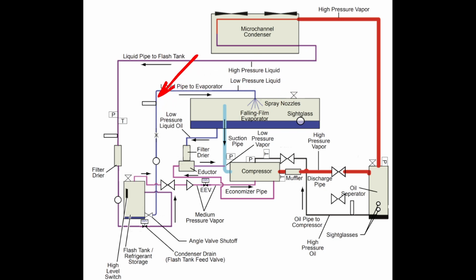Either way, our refrigerant gets injected into the top of the evaporator. There is a spray rail system in here that sprays this refrigerant over the tube assembly, and then our suction line also comes off the top of the evaporator as well. So we don't have any lines or connections here at the bottom of the evaporator except for our oil recovery tap for our eductor. So the way these are piped, I'm going to start off over here on the high pressure